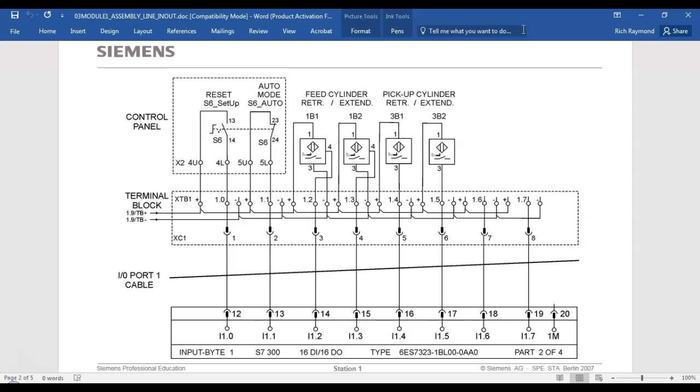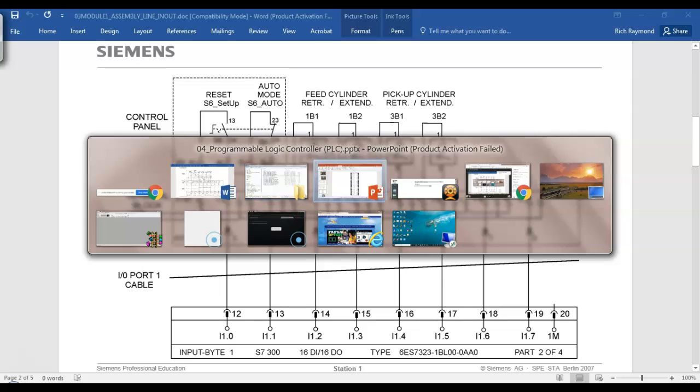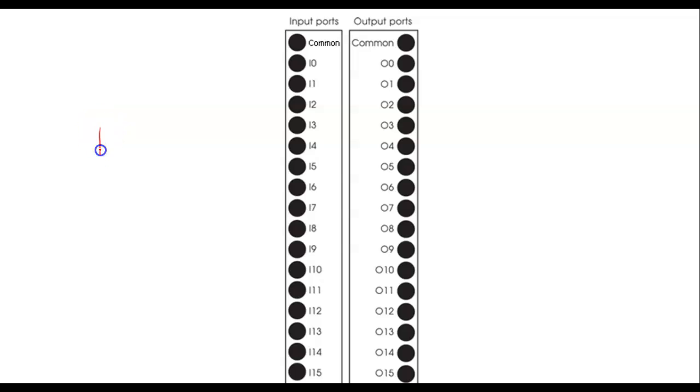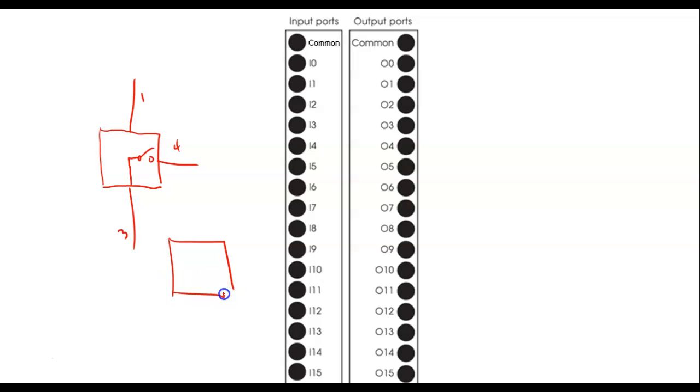1, 3, 4. It's just what it's going to do is switching. So what a sinking sensor would do is, I'll have to bring up a PowerPoint. And this would be 4. But the other sensor, so this would be an NPN sensor. The other one I still wired up exactly the same, except what it does, it comes over here and switches this one to the output. And this is still labeled what? 4.